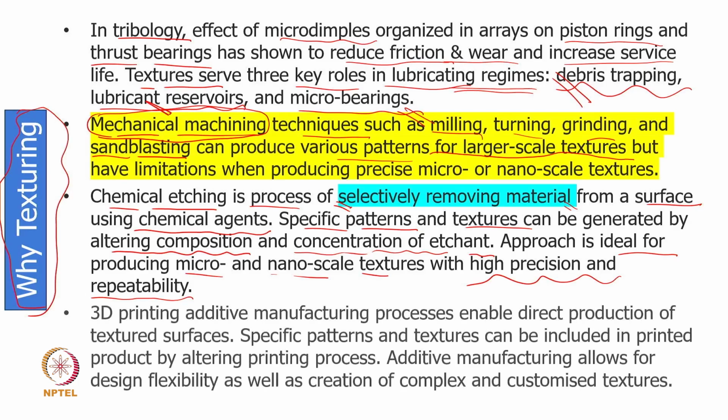So, chemical etching may give very good surface precision, but if we want better, then we need to do post processing on that. Now, there is another thing which we also use: we first put down a layer, then chemically select it and remove some portion of the layer. It can be 25% removal, it can be 30%, it can be 50%. So, why do we really do that? Why not go ahead with additive manufacturing itself? Wherever we require material, you deposit. Why do you want to remove material and create more and more wastage?